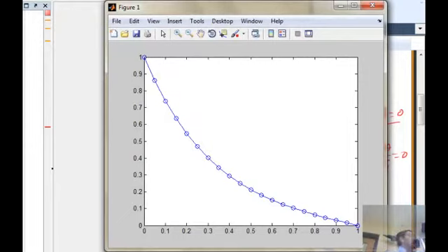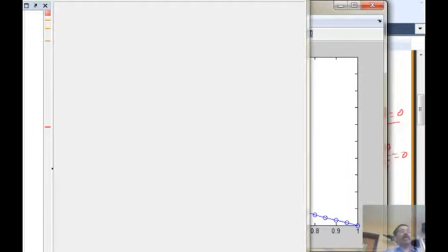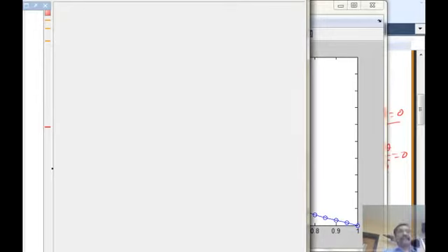Immediately I should recognize I need to put a loop. The loop around what? Loop around lines 3 and 4, because line 3 solves it, line 4 plots it. How many times do I put the loop? As many H as I want. So I create a vector H for heat transfer coefficient, maybe 5 numbers, so I want to solve for 5 cases. And I want to set up the value of H in the calling function and ask it to be picked up in the fin function automatically. How do I do that? Using something called a global variable.